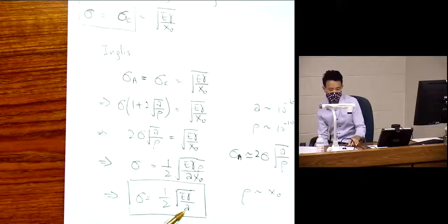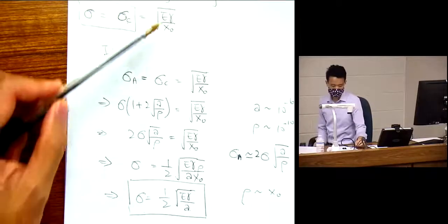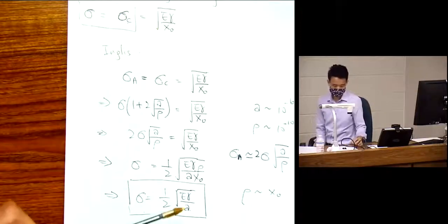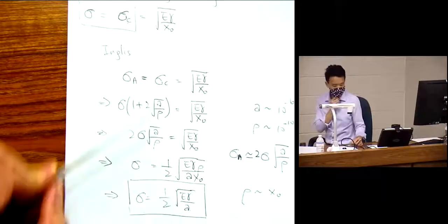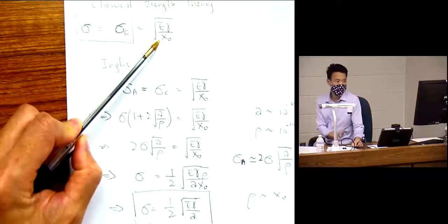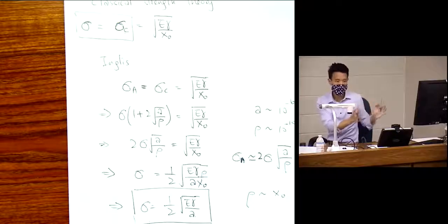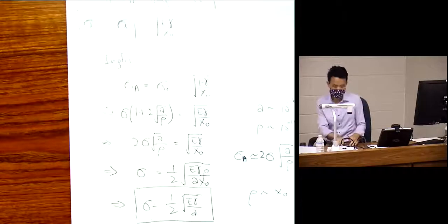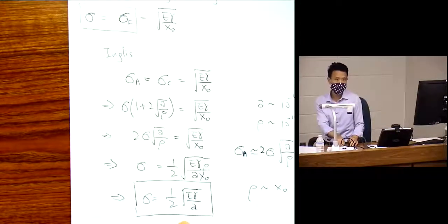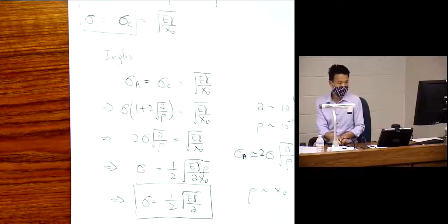If you just compare these two, you're going to see that the dimension exactly scales with the flaw size, right? Because over here, what you get is on the order of angstrom, and it really depends on the material. It doesn't matter how many cracks are in there. You get the chemical composition of the material, and then this one is set. But here it is not. You get the same material, but if there are more cracks in this one than the other one, they're going to have different strengths.